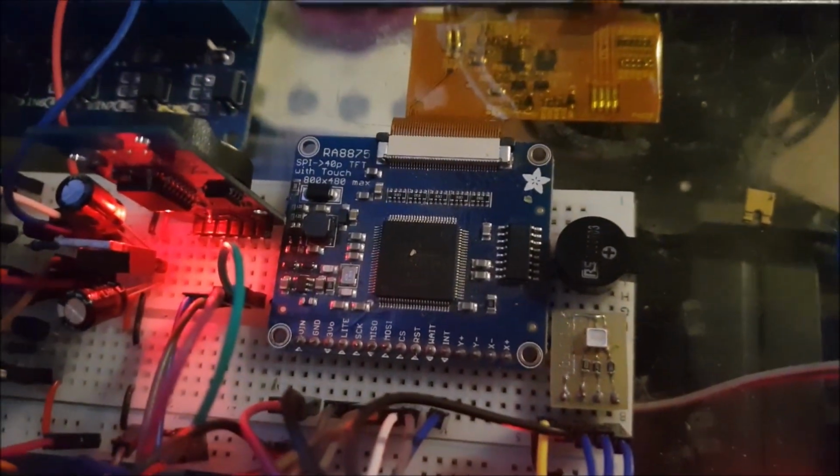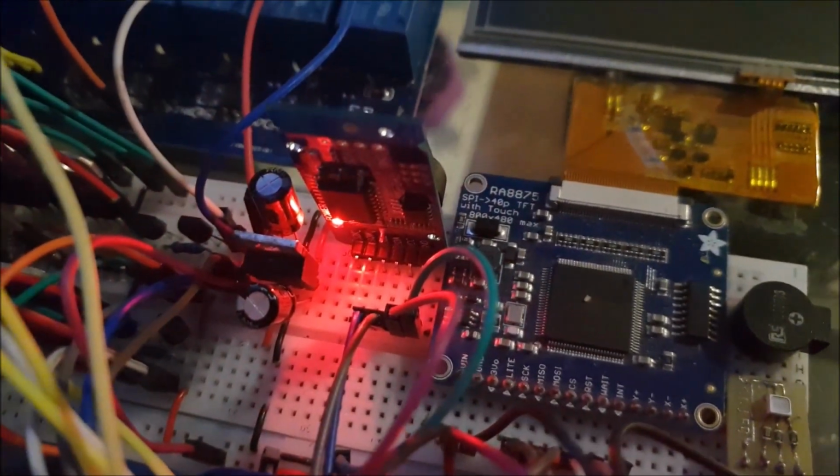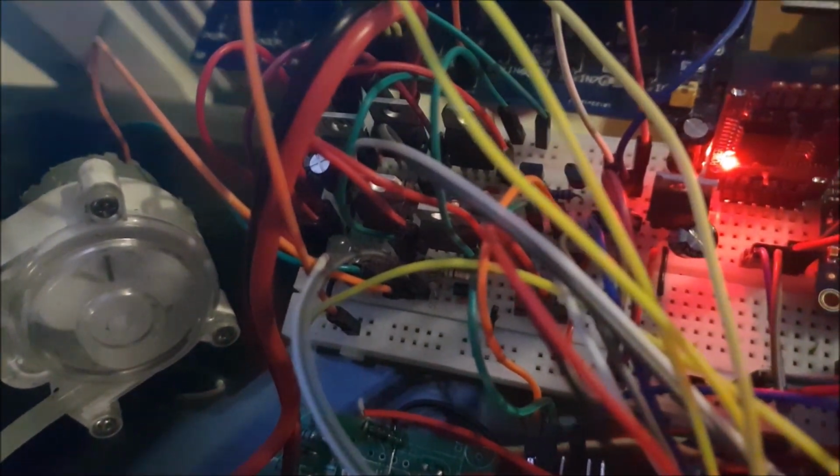You can just use the original tutorial for how to connect the display driver, an RGB LED. The speaker is just one wire. The RTC clock is your standard tutorial. The motor control via MOSFETs, well, you might need to Google that a bit. I suppose that's a circuit I will need to make. What circuit diagram I need to make is at least the MOSFETs, and if need be the transistor circuit. Again, it's just 2 transistors and a resistor. I suppose you need to know exactly which way around the wires go, so we'll make both of those circuits for the transistors and the MOSFETs.